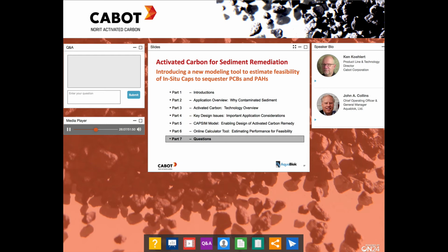contaminant will tend to block pore structure of the activated carbon. A lot of times in situations where we know that there's going to be a high degree of NAPL, we'll do kind of a treatment train approach and maybe use organoclay-based materials in front of activated carbon. We've done that both in sediment applications and in permeable reactive barrier applications where we knew NAPL was present.